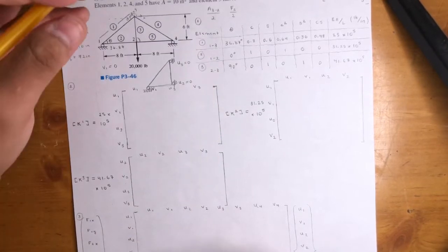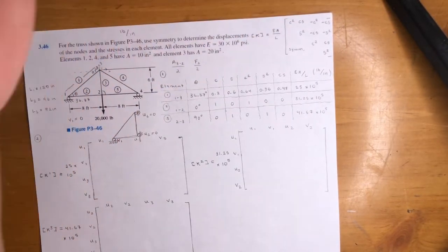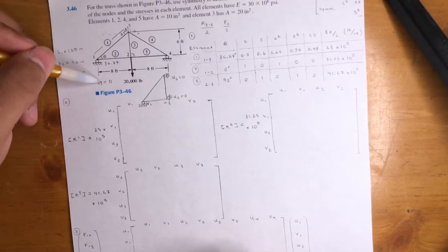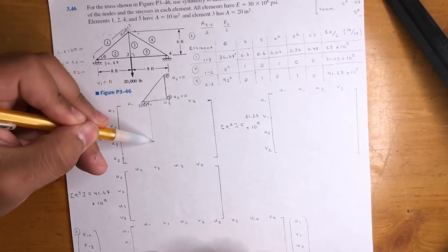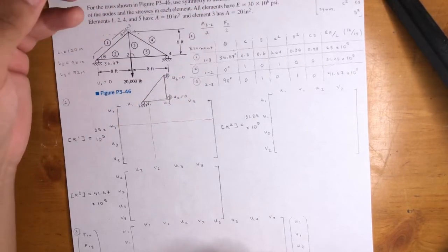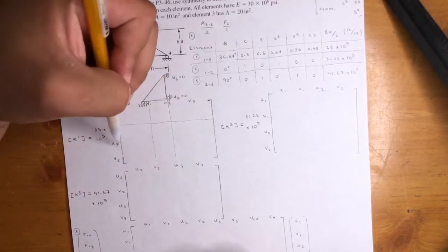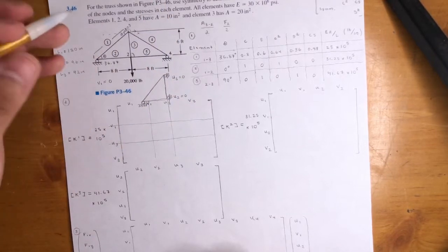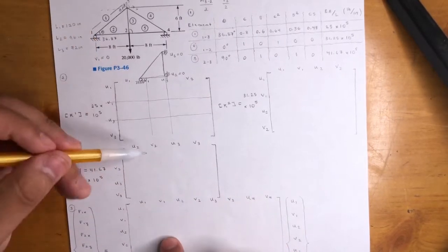All right, before we start filling in the table, you could do it. This one is a 4x4, which is not that bad compared to 3D. But let's start applying the boundary conditions first. We know V1 is 0, U3 is 0, and U2 is 0. So V1 is 0, and this gets canceled out, and this way too. What else? U3 is 0, which is this one right here, so that gets canceled out. It goes up and down and side to side, not just up and down. U2 and U3 in this case, so right here.